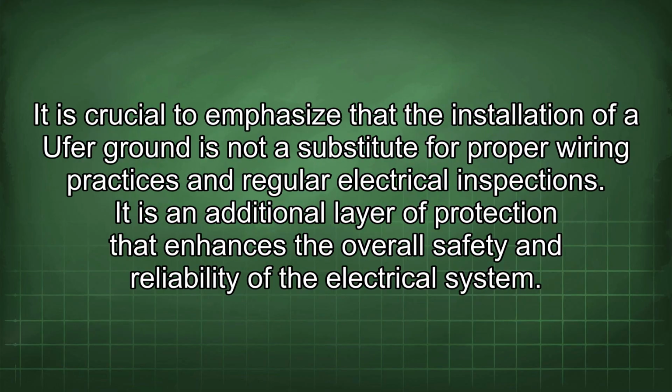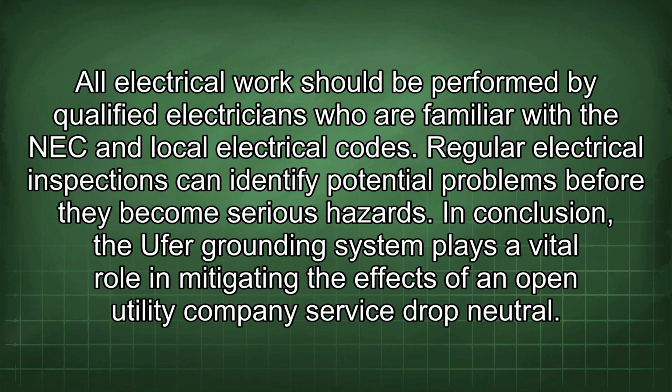It is crucial to emphasize that the installation of a Ufer ground is not a substitute for proper wiring practices and regular electrical inspections. It is an additional layer of protection that enhances the overall safety and reliability of the electrical system. All electrical work should be performed by qualified electricians who are familiar with the NEC and local electrical codes. Regular electrical inspections can identify potential problems before they become serious hazards.